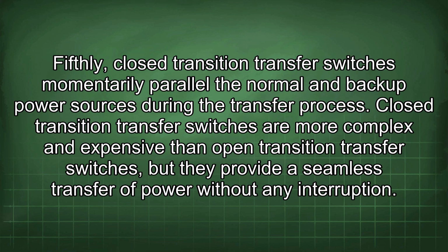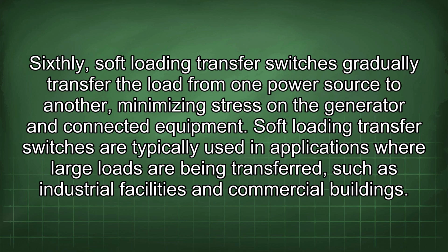Fifthly, closed transition transfer switches momentarily parallel the normal and backup power sources during the transfer process. Closed transition transfer switches are more complex and expensive than open transition transfer switches, but they provide a seamless transfer of power without any interruption. Sixthly, soft loading transfer switches gradually transfer the load from one power source to another, minimizing stress on the generator and connected equipment. Soft loading transfer switches are typically used in applications where large loads are being transferred, such as industrial facilities and commercial buildings.